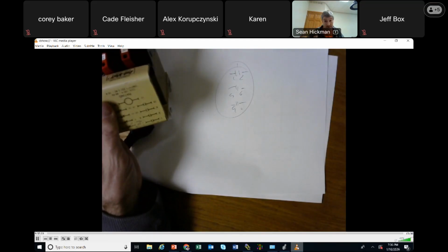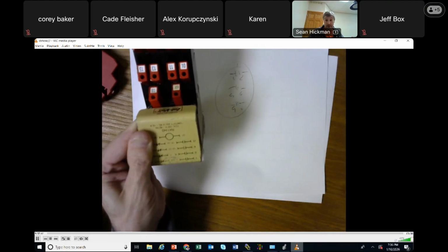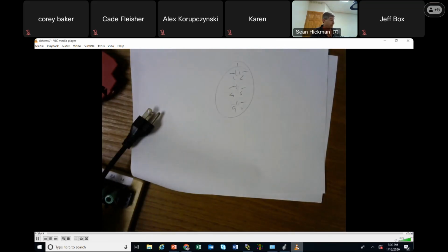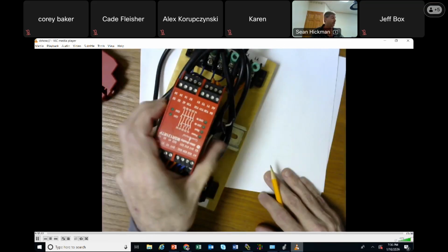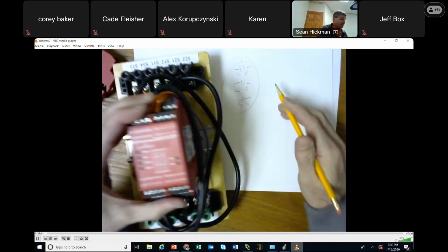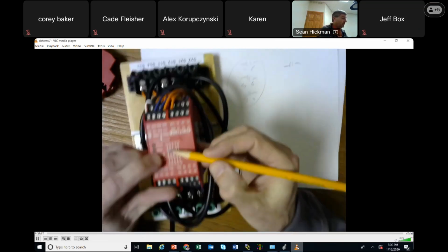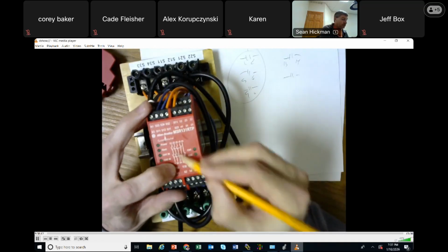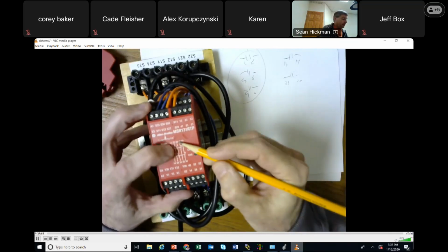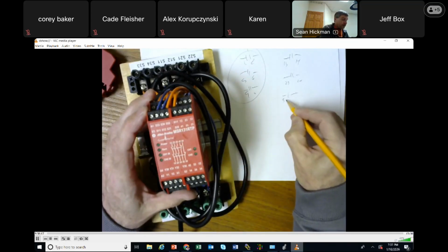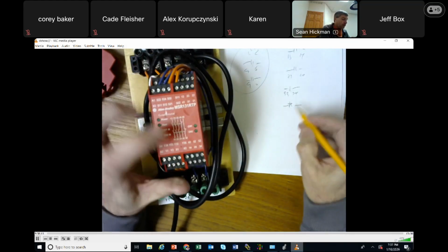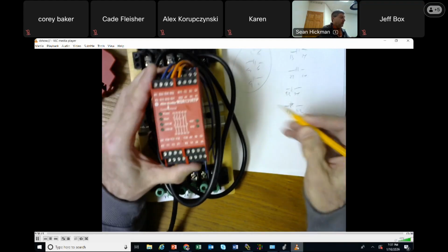So 1 to 10, before I lose you, you agree on this. Turn this on, all those contacts close. You with me on this? Got it? Okay, wonderful. So when I turn this one on, what this says is that I got this contact, 13 and 14. 13 and 14 closes. And 23 and 24, and 33 and 34. And it's also got closed contacts. These ones open, and it's 41 and 42 and 51 and 52.